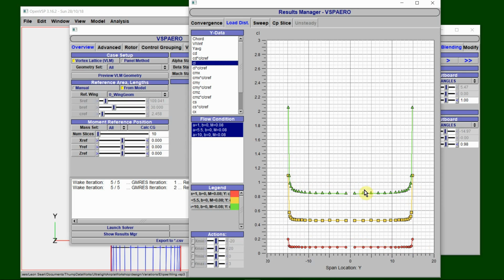It's when you start getting up to the higher angles of attack, this one's the 10-degree, that you start seeing some significant increase in the coefficient of lift. But for the most part, we came close. So I'd say that this program at least comes somewhat close to what we expect, according to Horner. So I think it is good enough to go ahead and design our wing. So that will be the next step. Let's go ahead and take a shot at designing our own wing. So that's the next thing to do.